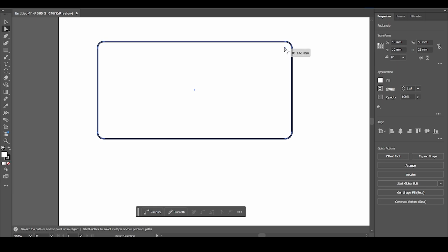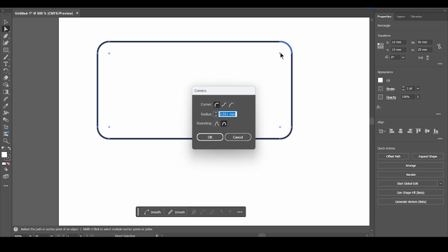All right. If you've watched a few of my videos by now, I love radiuses. I don't like sharp edges. So I'm going to throw in a 3mm radius. You'll notice that this is a click and drag option. I can't type in what I want, which is a little bit annoying, but 3.01mm is plenty good enough for me. The more you zoom in, the more accurate you can get that measurement, but that does all of them uniformly. If I wanted to just do one,